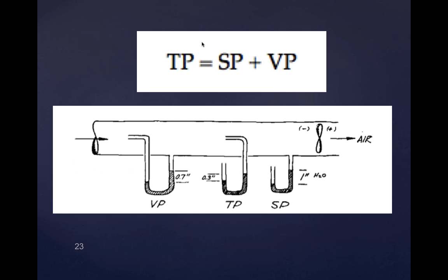It goes up. Okay, so it's a little bit tricky when we deal with it because the static pressure, most of the system that we're most concerned about is on the suction side of the fan. So the static pressures are negative numbers, but they still do the same thing, right? Well, maybe we'll get to an example. We'll actually work through it.